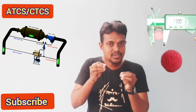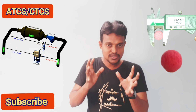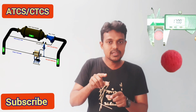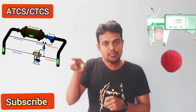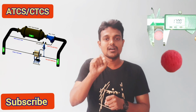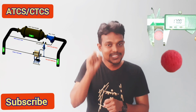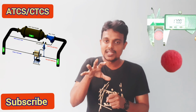Because of the water quality, and since this condenser circuit is an open circuit, a lot of particles may get into the system. Over a period, those particles form a small layer in the condenser tube. Because of that layer, that scaling, the performance of your system gets disturbed.